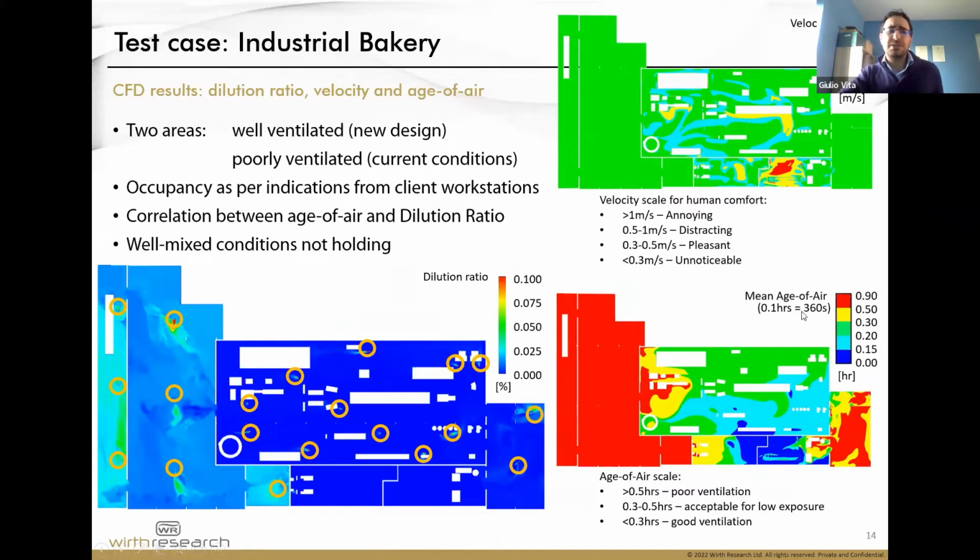So this parameter is actually quite important because it's a great way of showing where the problems occur, because it's very, very easily disturbed, let's say. The way I modeled this building is including openings in these 3 sides, which were not ventilated, and fully ventilating the area we were interested in. And as you can see, you can immediately see the difference in the ventilation performance.